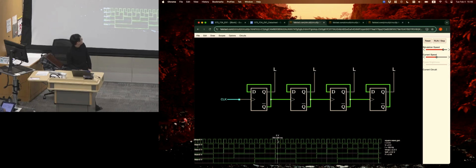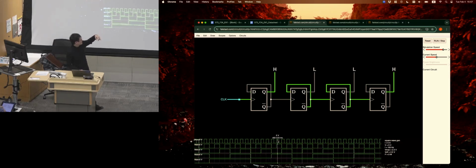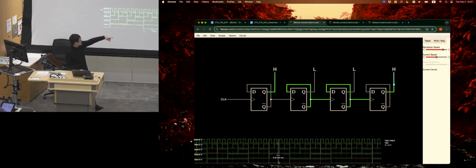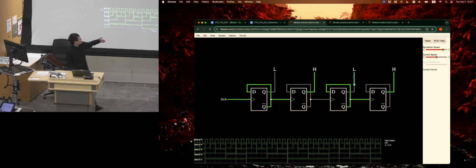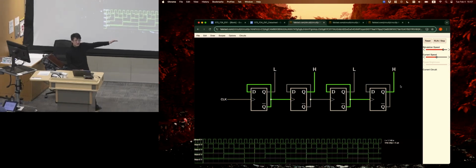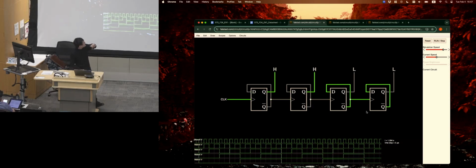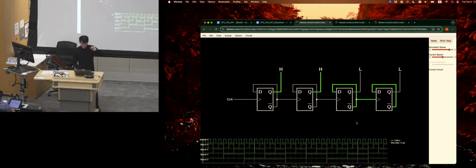The first one is the actual clock, and every time it goes through a stage, because of the Q and not Q connected together, it gets divided by a factor of 2. And at the end, depending on how many you connected, each of these outputs is dividing the signal by a factor of 2. I hope this is pretty straightforward. Okay, perfect.